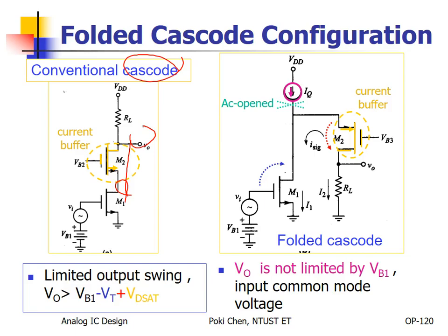Okay? But by the way, also decrease the input resistance because you need to absorb 100% of the current into M2, then push to the output. So hopefully, zero input resistance for M2, and infinite output resistance for M2. So this is the major purpose. Please keep this in mind.